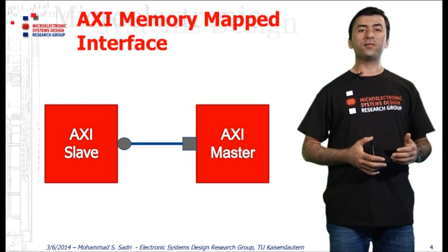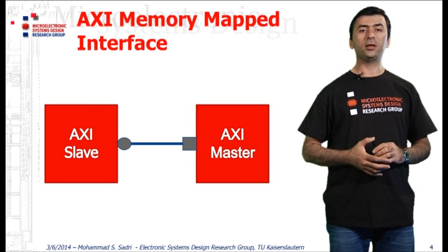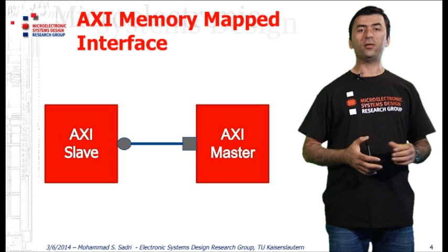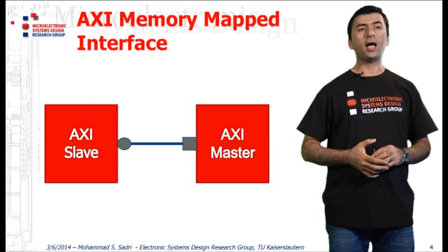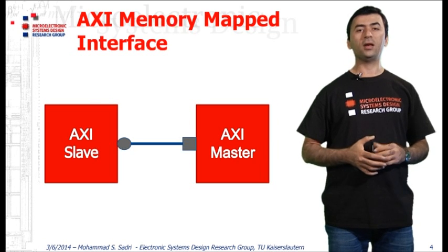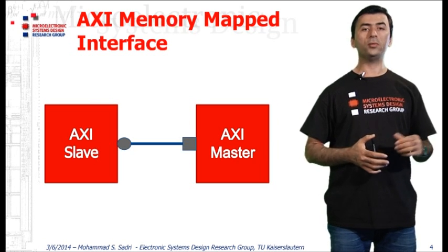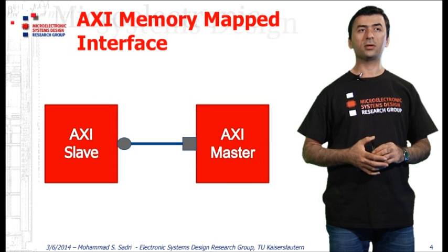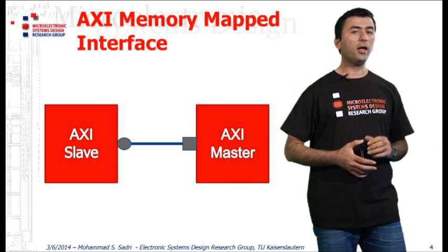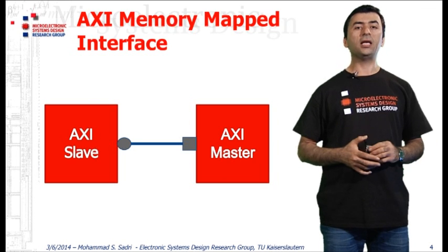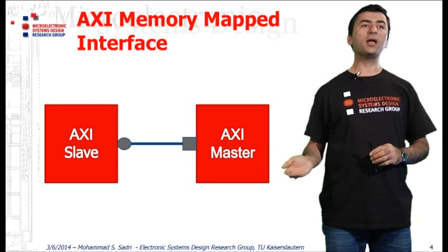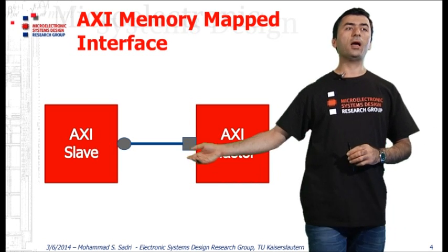Towards this, we have seen several standards appearing in the design community by big companies to solve this problem. AXI is one of them. Very basically, AXI is a standard through which different components inside your multi-component chip can talk to each other. Every AXI link contains necessarily two parts: one AXI master and another AXI slave.